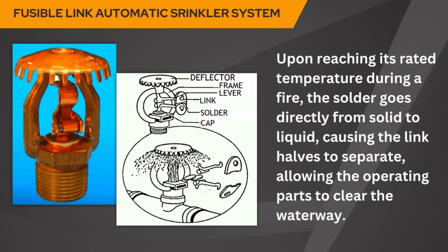Now, upon reaching its rated temperature during a fire, the solder goes directly from solid to liquid, causing the link to separate, allowing the operating parts to clear the water way.